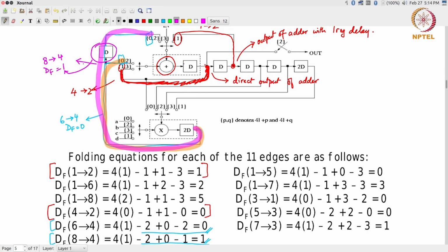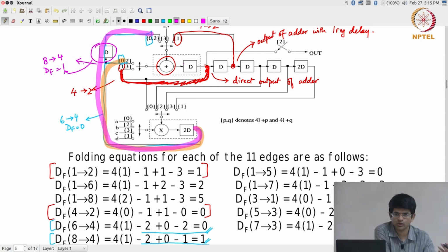First put down these two blocks, one adder, one multiplier. Okay. Then put down the different phases 0, 1, 2, 3 for each of the inputs. Okay. At phase 0, what is the operation that's being executed on the adder? Find out where its inputs are coming from. Find out what are the df values on those links. Put an appropriate number of registers to delay those links and then connect them up to the appropriate phase.